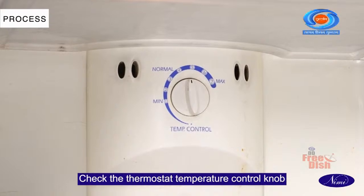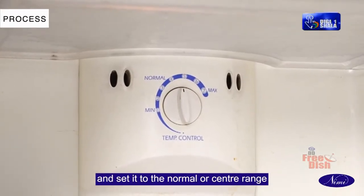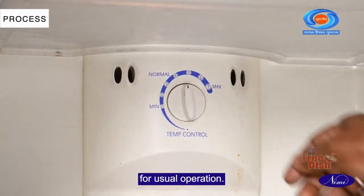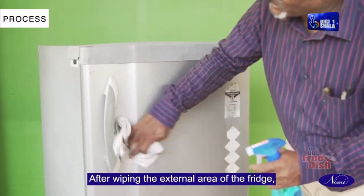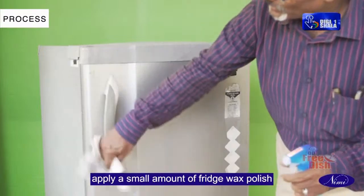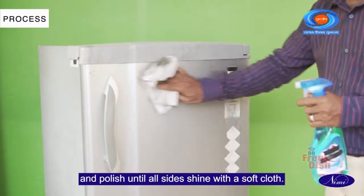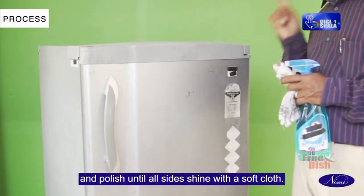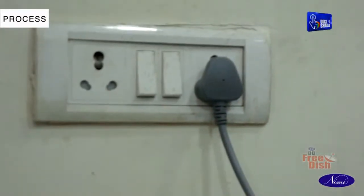Check the thermostat temperature control knob and set it to the normal or center range for usual operation. After wiping the external area of the fridge, apply a small amount of fridge wax polish and polish until all sides shine with a soft cloth. Connect the plug and switch on the refrigerator.